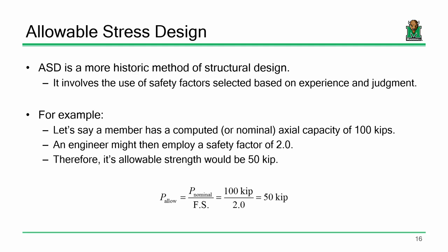Now, here I am sitting on the table, sitting in the middle. I'm in three-point bending. Now, let's say instead of me sitting on this table that this is some actuator in a lab. I've taken this table down to the lab, and I've put a load right here, and I'm pressing on this table, and I'm going to load it until failure, because, of course, any day with controlled demolition is a good day. So I load, and it fails at 800 pounds. I just made that up, 800 pounds. So what I'll call the nominal capacity of this table is 800 pounds. In other words, if I physically take this table and put 800 pounds on it, it will break.